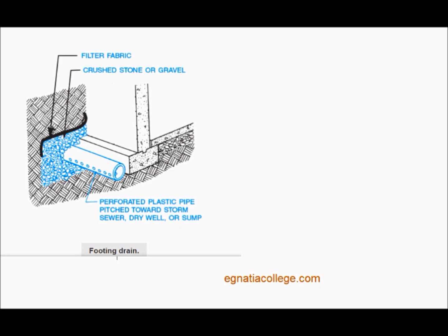After the foundation walls are erected and before the excavation outside the walls is backfilled, filled with earth to the finished grade line, footing drains, if indicated, must be installed. Footing drains are usually perforated plastic pipe placed around the footings in a bed of crushed stone.